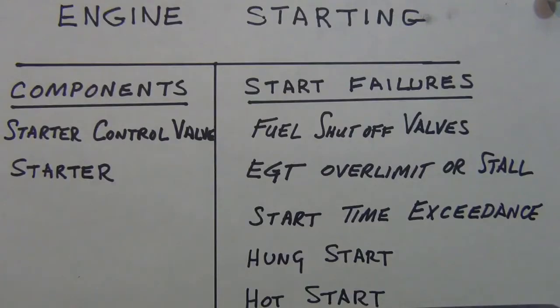And then there has to be a rest in between, because if you keep running it continuously without rest, it's going to get hot. You're trying to make sure you have some cool down in between, and that's why there's that 20-second rest in between. After the 4th cycle, you're going to allow more time for it to cool: 15 minutes lapsing to cool. There are other combinations, but I'm giving you the standard, regular duty cycle.